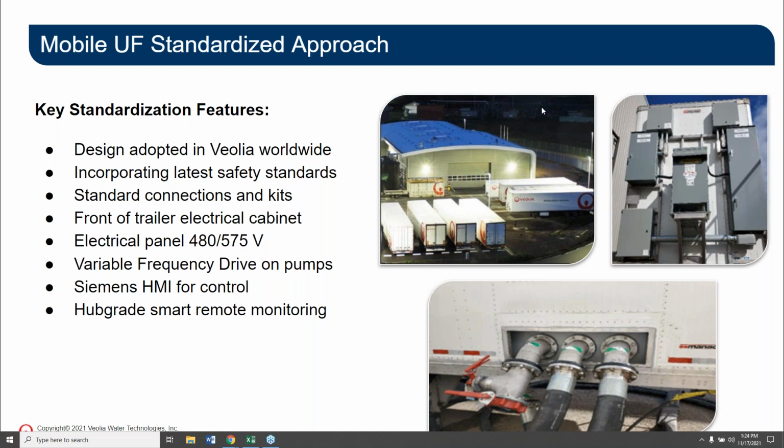this is key in cases where you have a high scale potential, such as the cases we find in the mining market. The water is just about to scale once you start changing the chemistry, and you do change the chemistry when you prepare the chemical solutions using filtered water. So you don't want that to happen and start making the membranes dirtier while cleaning. So you can use an external source of water, whether that be an RO permeate or an ion exchange demineralized